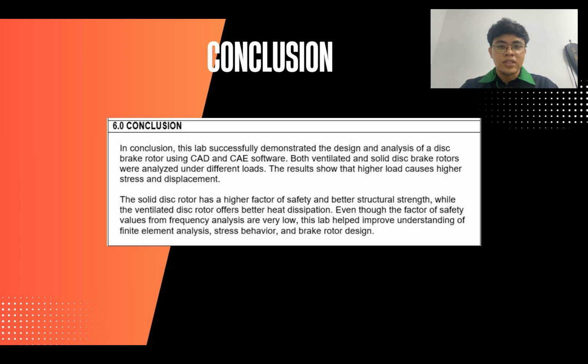The solid disc rotor has a higher factor of safety and better structural strength, while the ventilated disc rotor offers better heat dissipation. Even though the factor of safety values from frequency analysis are very low, this lab helped improve understanding of finite element analysis, stress behavior, and brake rotor design.